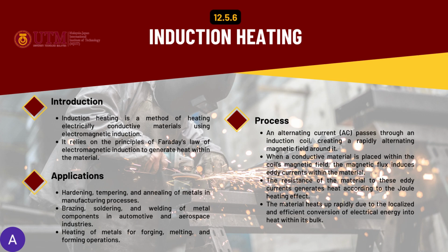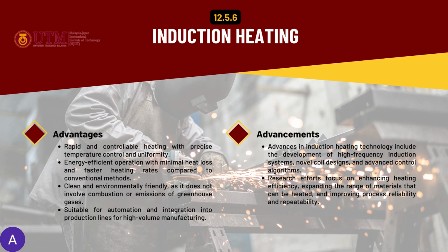Common applications for induction heating are hardening, tempering, and annealing of metals in manufacturing processes. Also heating of metal for forging, melting, and forming operations. The advantages of induction heating are rapid and controllable heating with precise, energy efficient operation, clean and environmentally friendly, and suitable for automation and integration into production lines for high volume manufacturing.